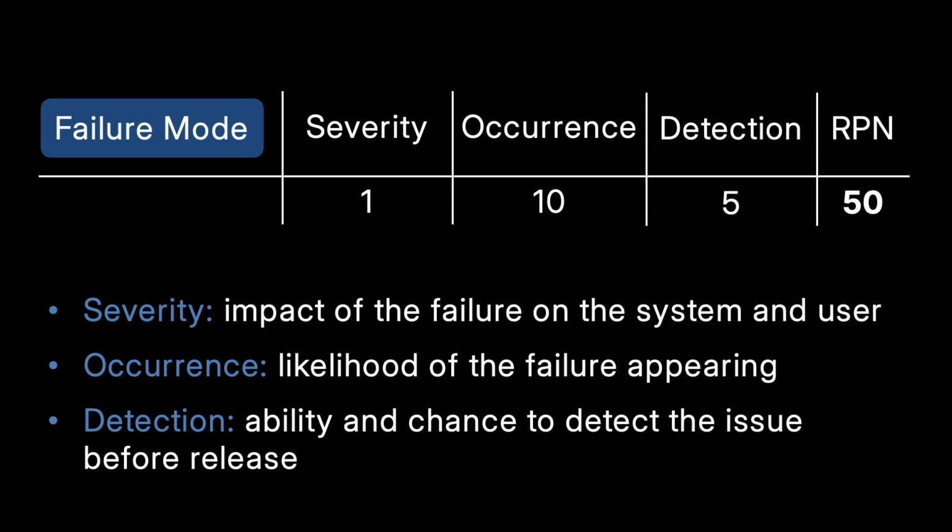Also, as one person usually cannot be the expert for everything, it also makes sense to involve cross-functional experts to gather further insights and feedback about the FMEA. And if available, it of course makes also sense to take past experiences into account for the risk analysis. Usually more than one failure mode per system is identified and can be reflected in a table. The table allows then also to prioritize the mitigation and failure modes easily by sorting them according to the highest RPN.